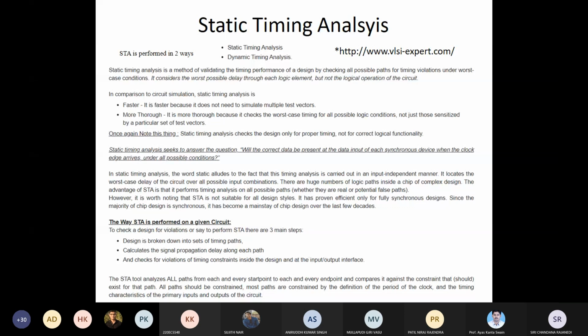Okay, so that's why you can just imagine this gate level netlist, which is again in VHDL or Verilog, is different from the RTL code, which is also in VHDL and Verilog. Okay, so when you compute with these gate level netlists, it will give you how much power it consumes, and what the area is. All these things we basically do in FPGA, but these are very much done at the ASIC level, the IC design level.